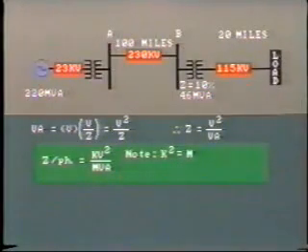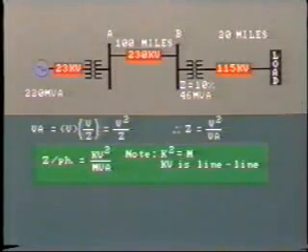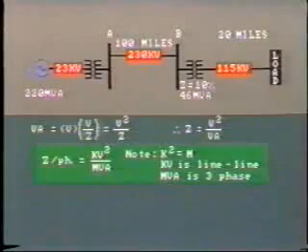In this expression, the kV and MVA units are quite compatible because we are squaring the kV and so bringing another 3 zeros into the top line. And by using line-to-line voltage, we get impedance per phase. The MVA value is total three-phase. Verify these units using your workbook.